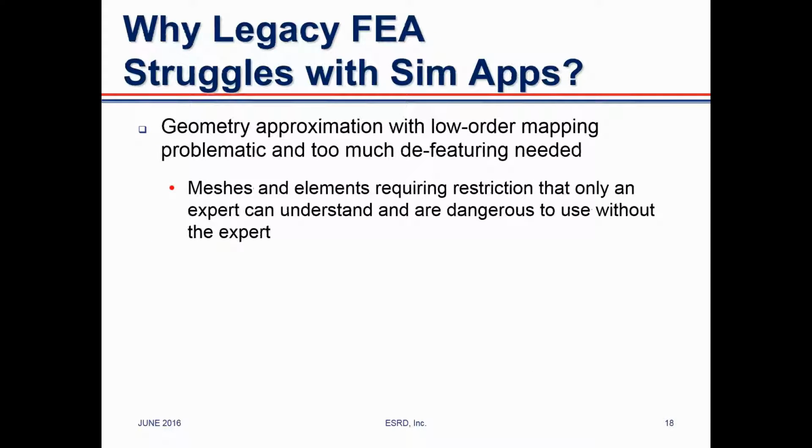One of the things that is important to remark is the fact that legacy finite element analysis software tools struggle with simulation apps. And what is the reason for that? There are several, and we are going to list just a few. For example, geometric approximation with low-order mapping is problematic, and in general that forces a lot of defeaturing of the models, which can be problematic if the goal of the computation is to determine large peak stresses.